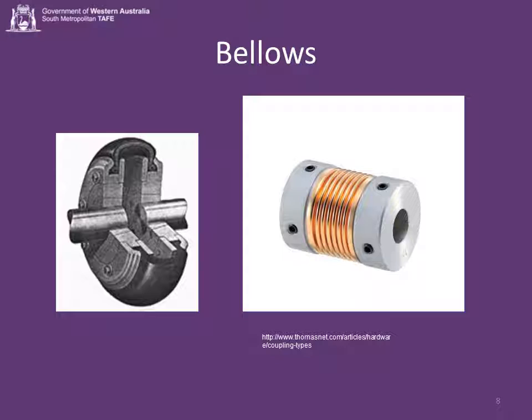There's two types of bellow coupling. The small bellow couplings are also for motion control applications. The large rubber bellow, sometimes called a flange coupling, are typically used for pumps and provide high torque transfer while dealing with large misalignments, axial, parallel and angular. Vibrational and torsional oscillation is damped by the rubber.